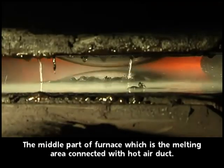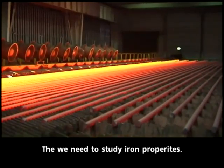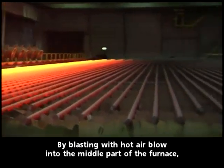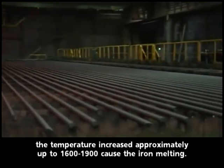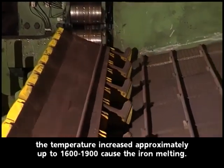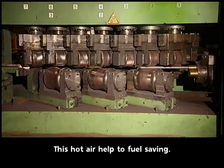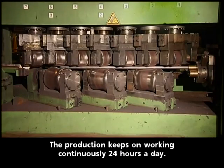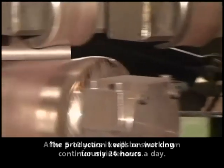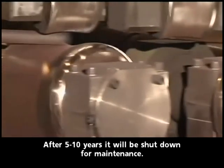The middle part of the furnace, which is the melting area, is connected with a hot air duct. By blasting hot air into the middle part of the furnace, the temperature increases to approximately 1600 to 1900 degrees, causing the iron to melt. This hot air helps to save fuel. The production keeps working continuously 24 hours a day. After 5 to 10 years it will be shut down for maintenance.